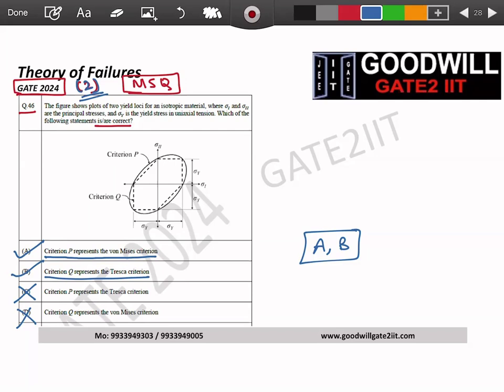Okay. I have a doubt. If due to cabin pressurization or even a hard landing the structure fails, isn't it a good idea to consider Tresca? That's what I'm saying. You're already carrying heavy weight with Tresca. Why consider that? We have a factor of safety with us, right, Priyal? Let's say landing gear has a factor of safety of 2, 3, maybe more. But there is no point in going with Tresca and having a heavier design, right? And you can go. I'm not denying that you cannot. You can propose, but the company will take it only if von Mises is giving you a lighter weight. Company will always go with that.